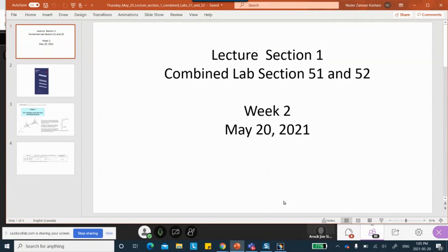Okay. I was thinking along the lines of axial constraints. Since that's possible when we're doing an assembly, I was thinking if that's possible also for analysis. Well, remember, analysis looks at what you gave it. If you gave it an assembly, it's going to require several parts. If you gave it a single part, then of course we are doing analysis of a single part. There are other things to do. So right now we are looking at a single part, and what you have in mind, I don't think is possible, or actually, you need to do it in the context that you have in mind.